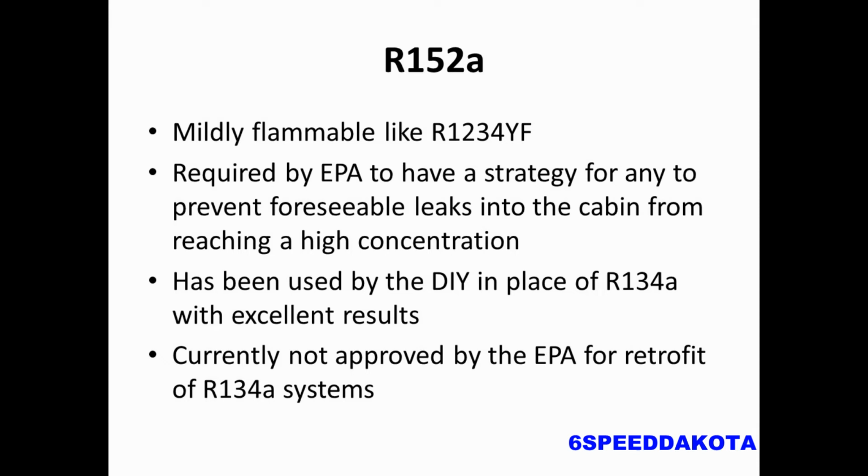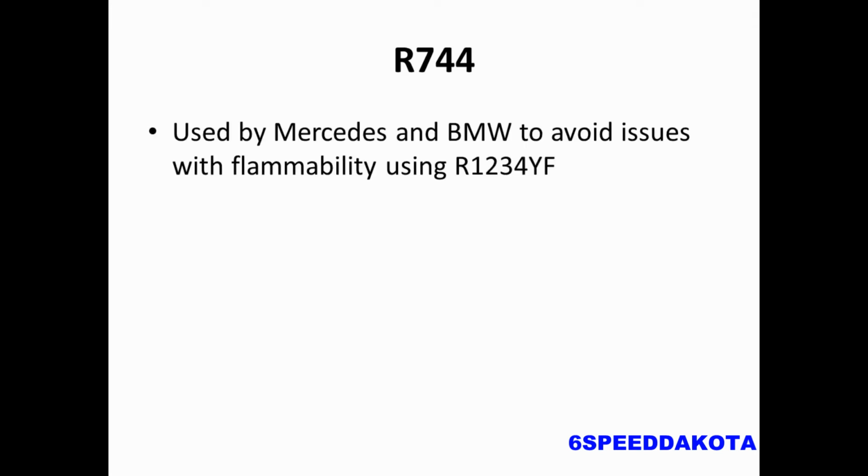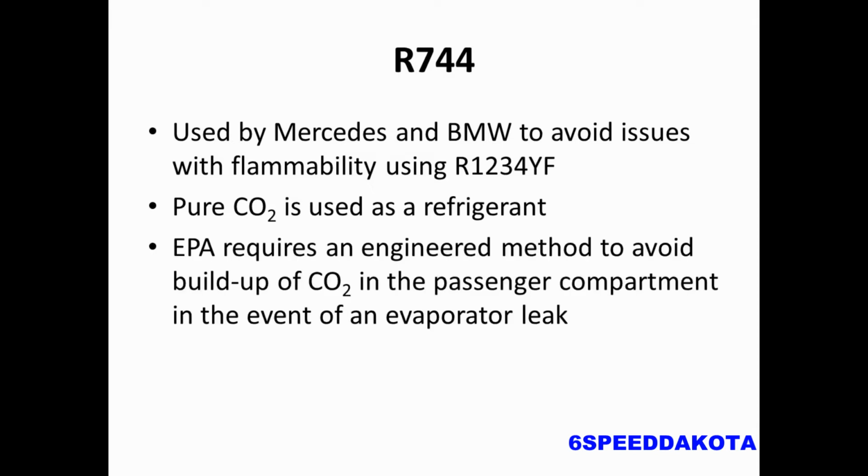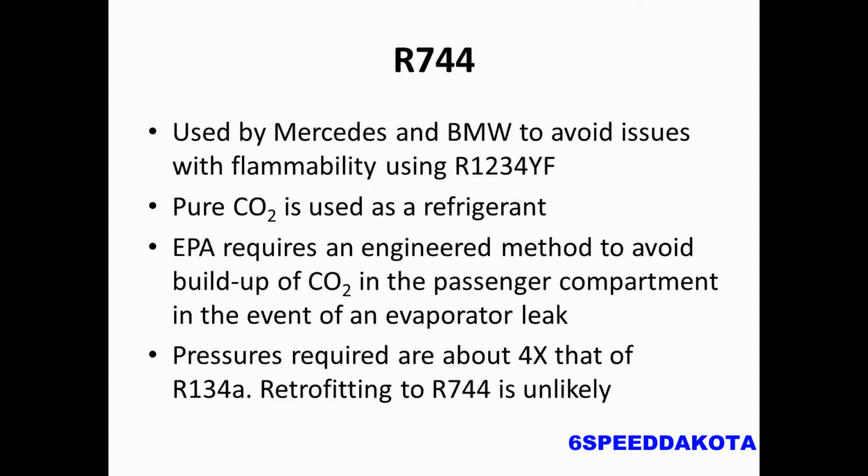R152A has a much lower greenhouse gas effect compared to 134A. And finally, our R744. This is actually used by Mercedes and BMW because of the flammability issues with R1234YF. Pure CO2 is actually used as a refrigerant, but the EPA requires an engineered method that avoids a buildup of carbon dioxide in the passenger compartment in the event that the evaporator decides to leak. This is so you don't die of asphyxiation inside the car.